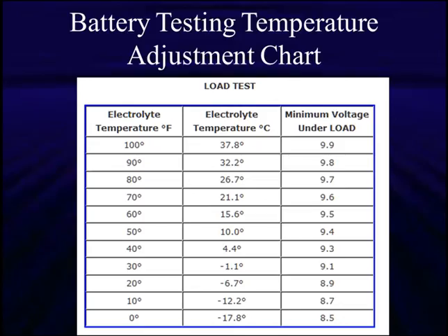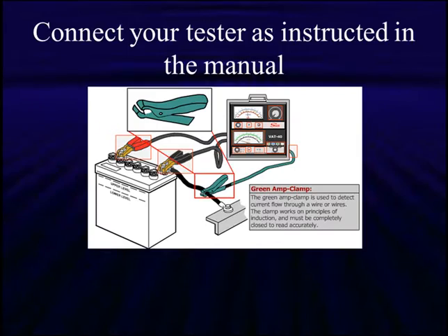The point we're making, understand what it is you're testing. Look at the details, because you might miss a battery that is marginal at 100 degrees Fahrenheit, which is not exceptionally warm. And if you look for a 9.6 volt load, you're already 0.3 of a volt wrong. It is not as good as you think it is. We're going to talk about some alternate ways of testing.